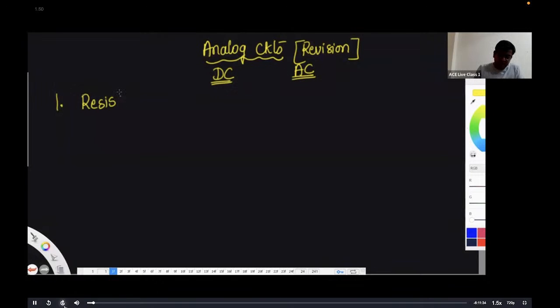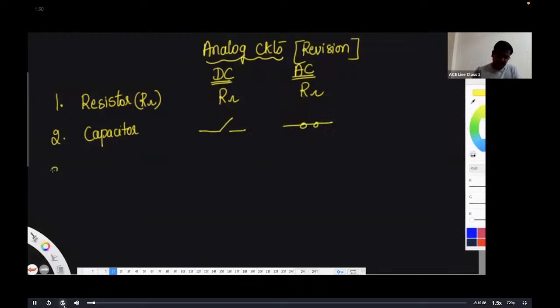Now, if you find any resistor in the circuit, resistor is not going to change its phase for DC and AC. So the resistance is R ohms, whether it is DC circuits or AC circuits. But if filter circuits are given, and you want to recognize the type of filter, then the circuit model you have to remember is capacitors. For DC, you can replace by open switch. For AC, short circuit. Inductor gives a complementary picture, short for DC, open for AC.